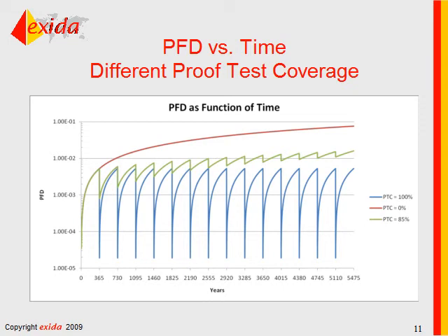And then we selected 85%, which again initially shows the same thing, but then what you can see here is that when you perform a proof test, PFD will not go all the way back to 0. It will continue to increase slowly, so that basically accounts for that portion of the failures that are not detected during the proof test.